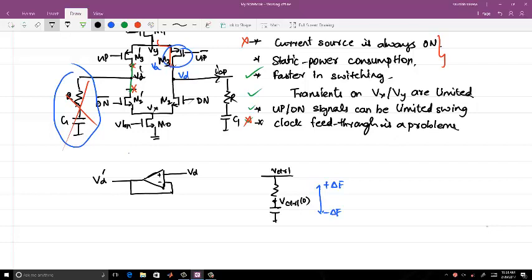So if you use a source follower, you can fix that VD and VD dash. Good question. Tell me which way we should connect. If VD is coming on the loop filter side, do you want to add an output impedance of an op amp there to change your loop filter gain? Or do you want to take the input gate capacitance into account in your loop filter and get rid of it? And the other thing is, what parameter is changing in the PLL and what do you want to change?